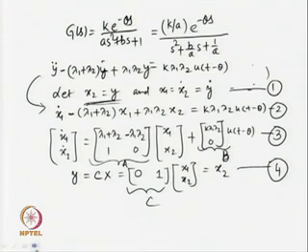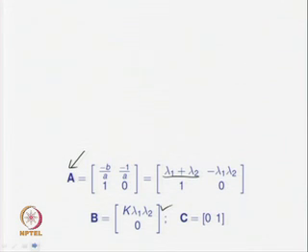And C is given by 0 1. So, why am I doing all this analysis? When we get the state and output equations expressed in some convenient form, the set of powerful equations we derived earlier for identification of second order plus dead time transfer function models can easily be extended to the underdamped second order plus dead time dynamics.